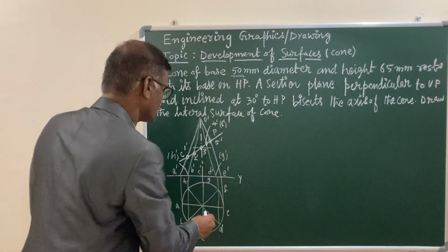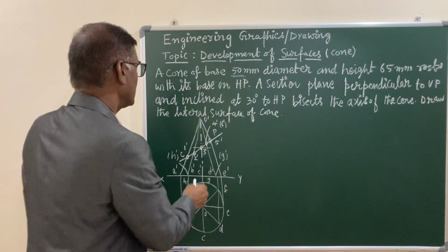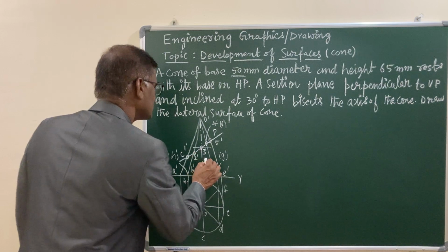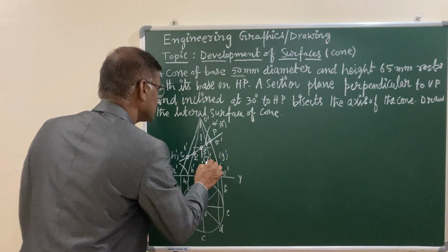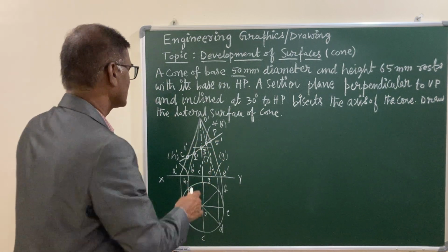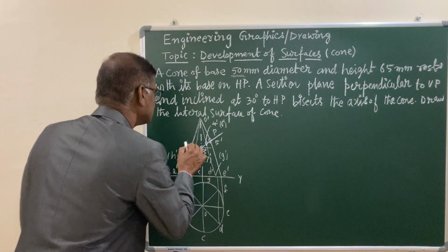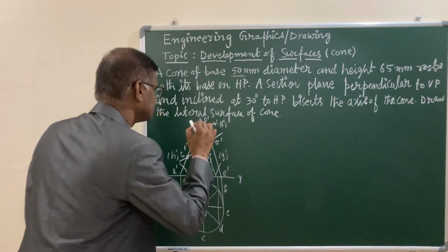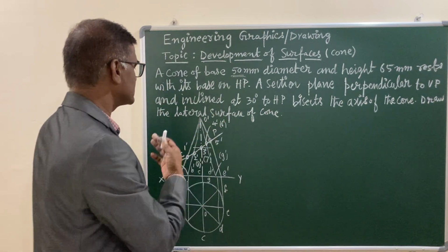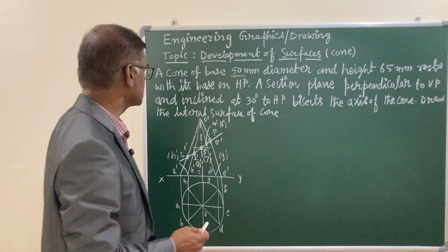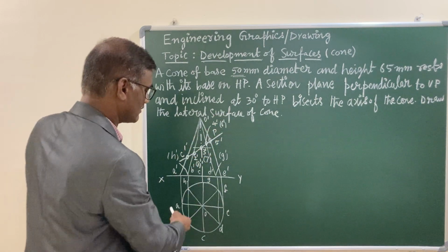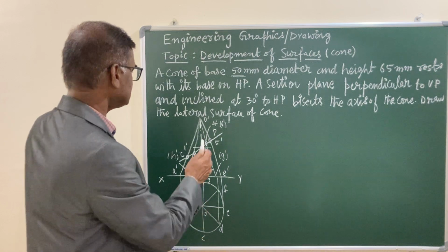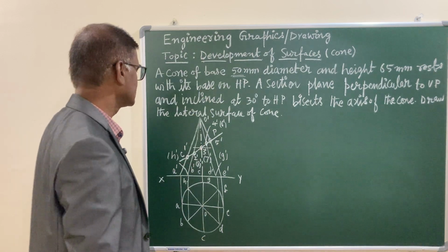exactly, which is going to coincide with your 4, and at 3 you have 7. So 7 you can keep in parenthesis, 3 and 7, and 2 and 8, 8 you can keep in parenthesis. So you have located the points of intersection between the generators. You divide into 8 equal parts. The representative generators are 8 and the cutting plane, right?